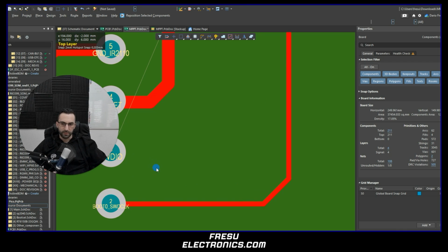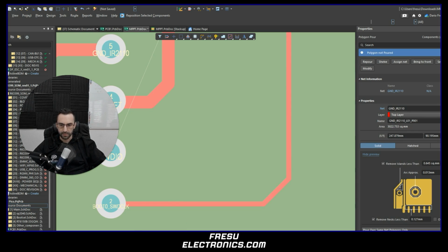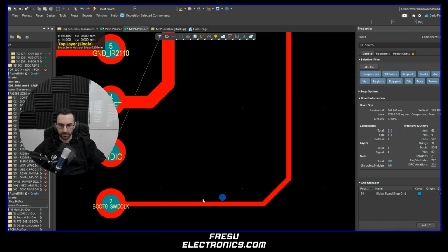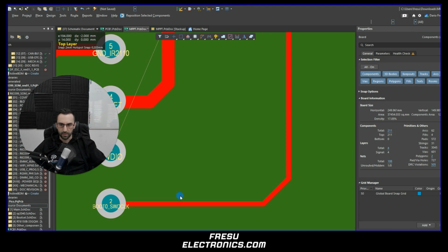So this is very important for us because what we can do with this information, we know that when we're doing the layout, if we have a high speed signal, the return reference plane, which is right now in the second layer, has to be as close as possible to the top layer in here where the signal trace is laid out.